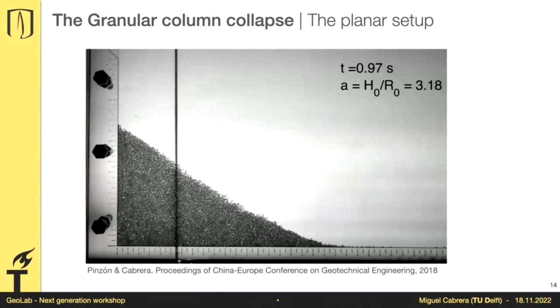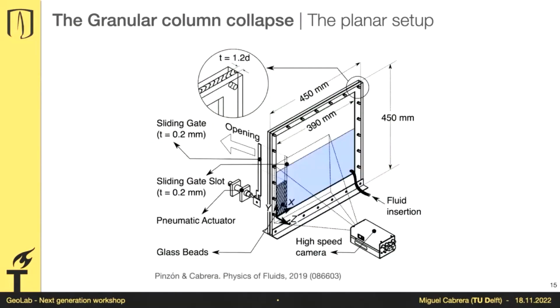So basically what we did to study landslide generated waves was to add some water, and look what happened. We added some water just by adding a little pipe on the side, filling in the gap. And here we had to be quite aware of the potential surface tension of water. Because if a collection of dry particles jump into water, surface tension might generate a capillary bridge that generates a bubble inside the soil. And that is somehow annoying because it dissipates momentum transfer.